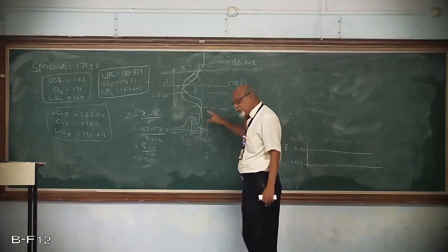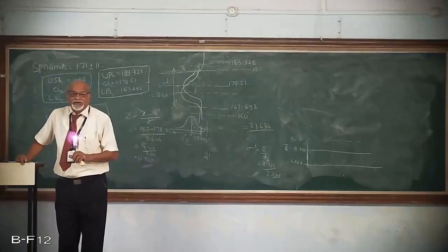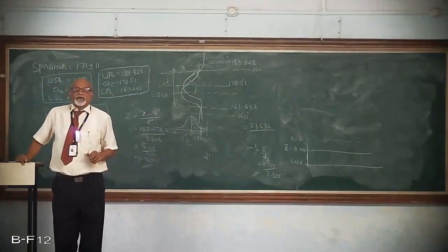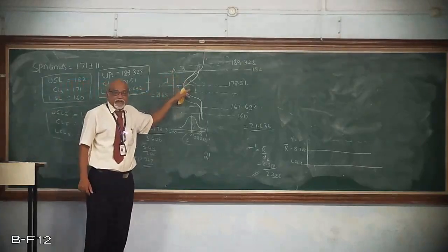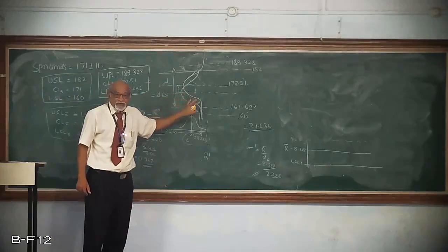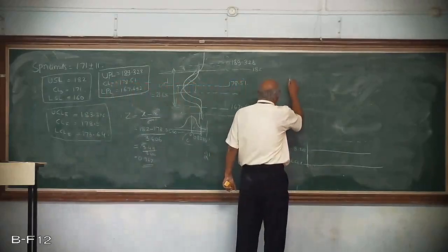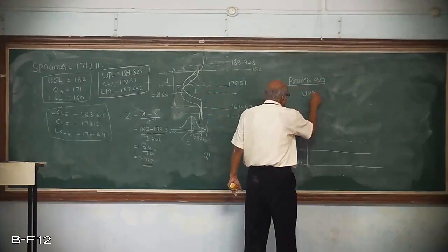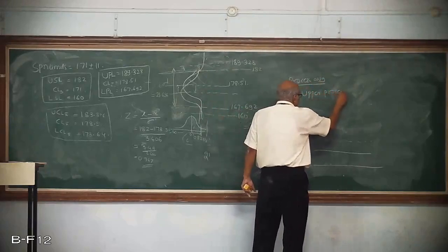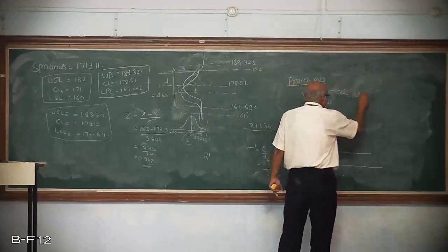Okay, in that case, I am going to produce some more defective parts, rework. No, not rework, it is to be scrapped. It is better to reduce the rework. Excessive rework is being done. It is better to reduce it and at the same time take care that no scrap is being produced. Okay. So here, in that case, how do I find out the new process average? I said make the upper process limit equal to the upper specification limit.